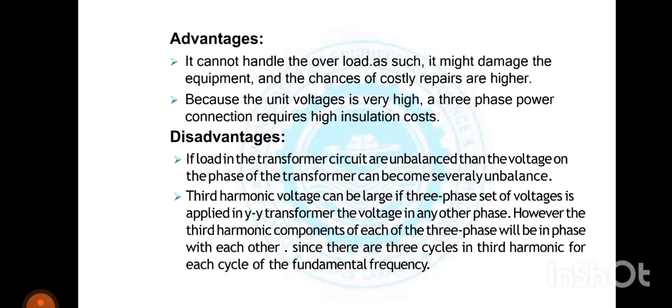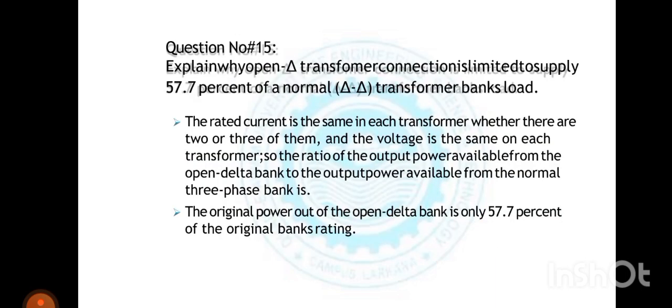The third harmonic components of each of the three phases will be in phase with each other, since there are three cycles in the third harmonic for each cycle of the fundamental frequency.